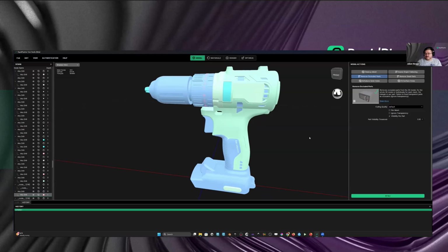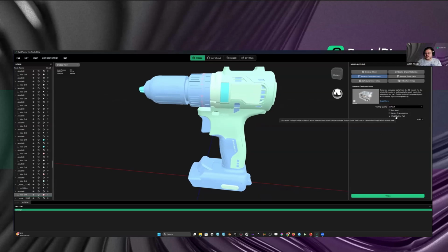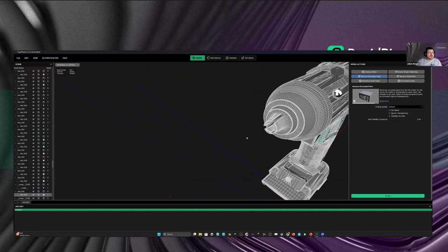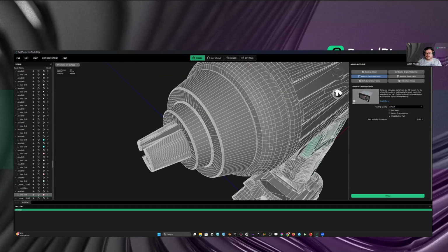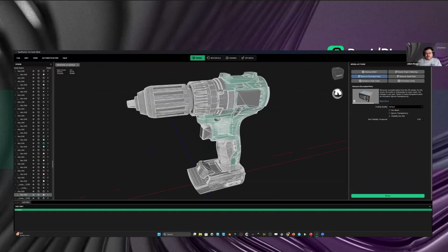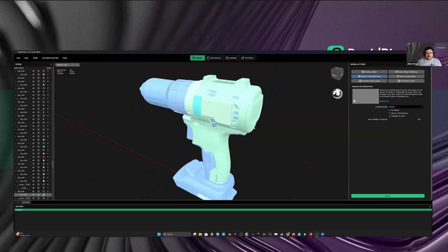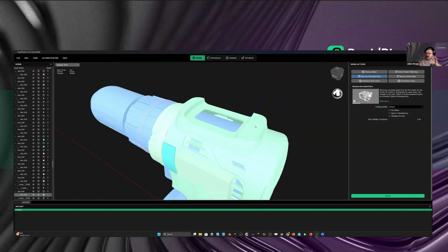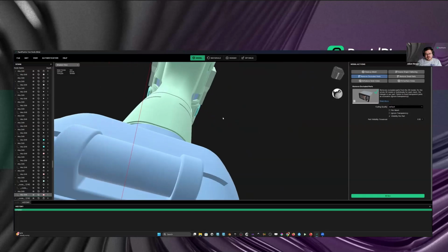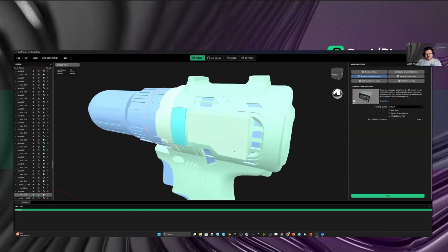The visibility per part is a bit similar to what I explained with the winding order. It will not leave behind single triangles. If you turn this off, it will really just check per triangle, or in this case per quad. Let me double check if that imported correctly. Wireframe on surface. So yeah, we have a few quads here, especially on the rounded parts. So it would compute per triangle or quad here. And then you would probably have what we would call a triangle soup inside, because maybe some of these faces are visible through some of these angles, because we have a few through holes where we could potentially, from a certain angle, when we cast a ray here, see parts of the interior.